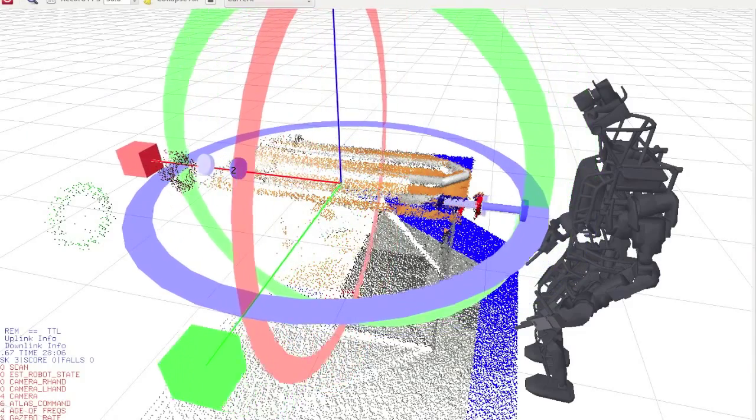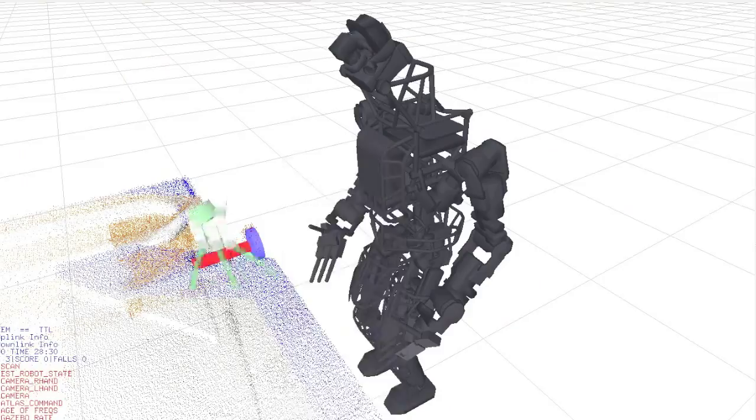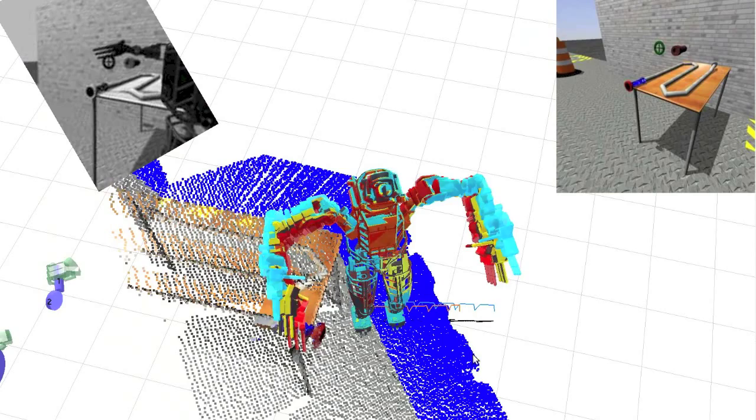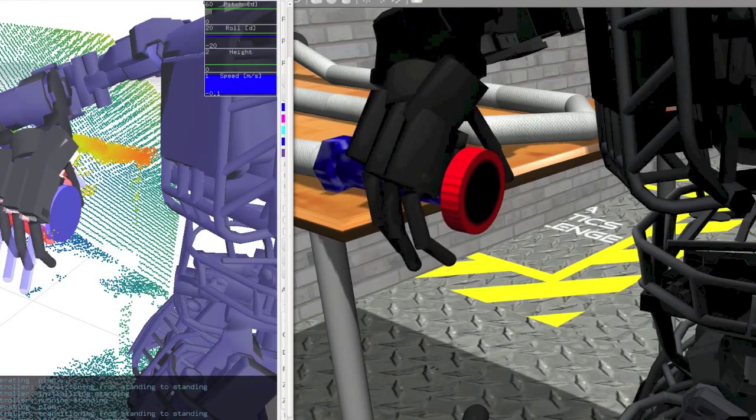The two main modes of our planning and control infrastructure were manipulation and walking. During manipulation, the operator requested the sensor data, fit object models, and generated robot plans. To initiate the manipulation of an object, a hand grasp was synthesized to create force closure. Next, our whole-body motion planner produced a reaching plan to place the hand at the desired grasp location.